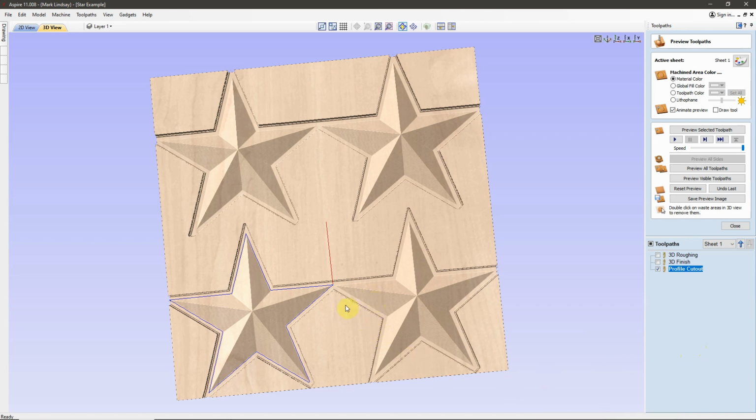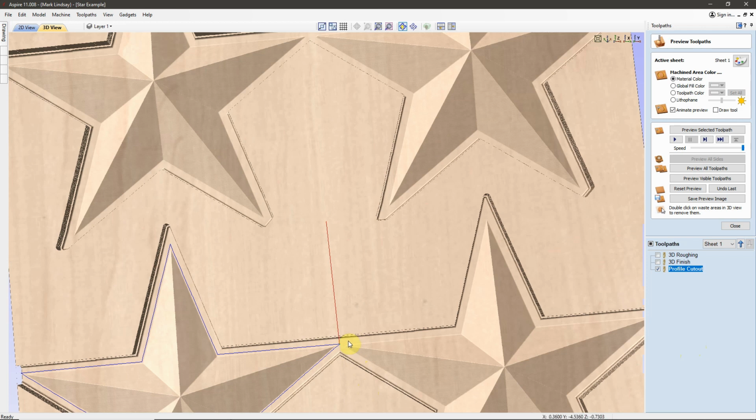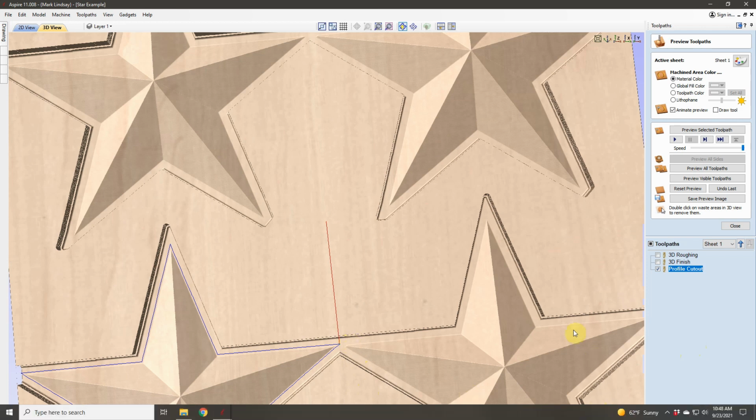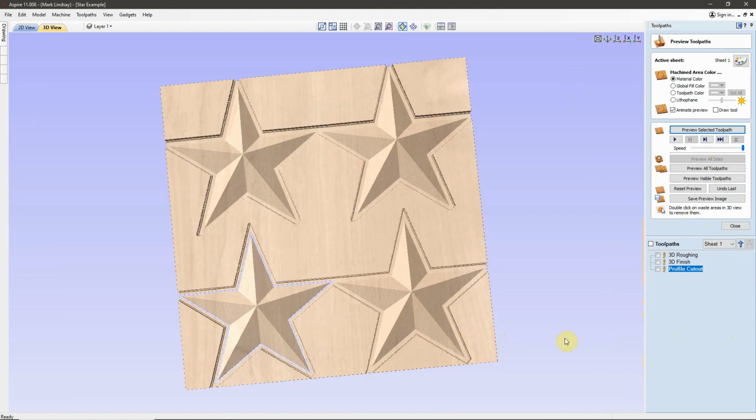We'll calculate the toolpath. Now, again, if we look down here in this space that's been machined away and you look at my readout down below here, you'll see that I'm at 0.73. That's why we're starting our cutout at that depth. So we'll preview that toolpath, and we see that it cut over here.